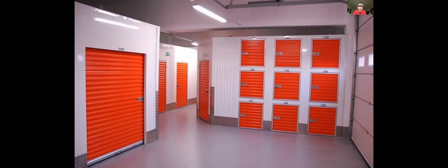So yeah, you need to have storage so that you can keep your payload data. This is the important stuff that you're generating, maybe you're taking pictures of the Earth, and then also logs of how the subsystems are faring. Are they doing their jobs correctly? Have they errored out? What is the temperature? How much solar power are we getting? That sort of thing. So you can send that all down and then have this package that you can look through to ascertain how well your satellite is performing.